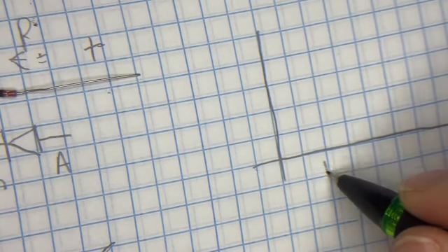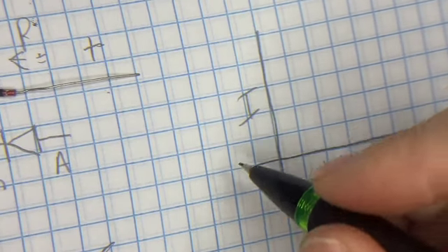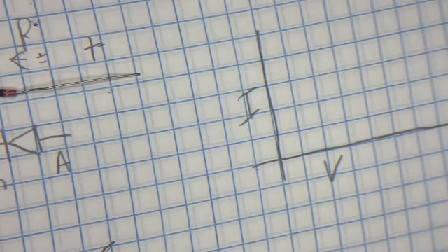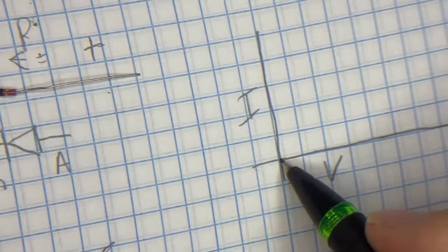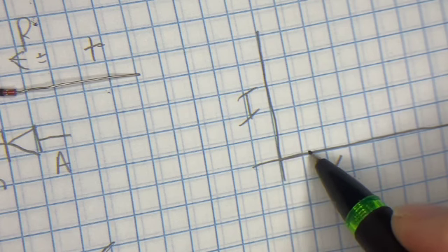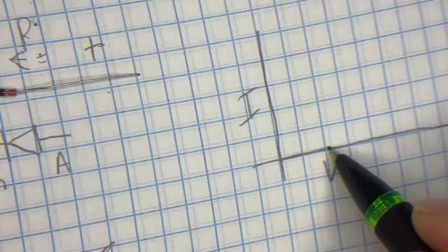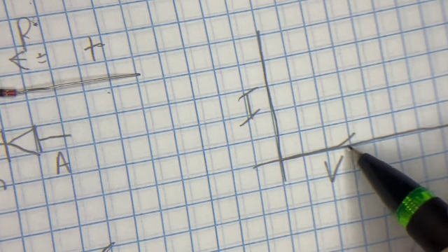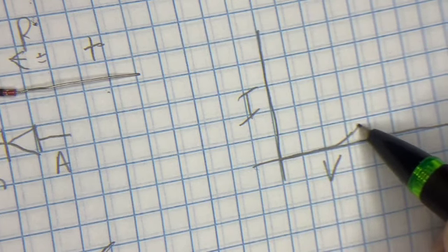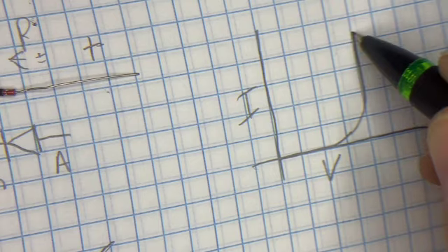we have the same thing here. We have the voltage and we have the current. Yeah, I know, I used the I instead of a C. So what happens is you put the voltage on and it doesn't do much until it hits that area of about 0.7 volts. And then it just shoots up almost straight up.